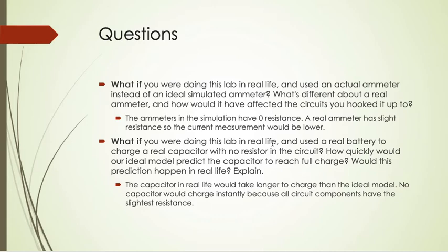Additional questions we had in this lab were: what if you were doing this lab in real life and used an actual ammeter instead of an ideal simulated ammeter? What is different about a real ammeter, and how would it affect the circuits you hooked it up to? The ammeters in the simulation have zero resistance, and a real ammeter has slight resistance, so the current measurement would be lower.